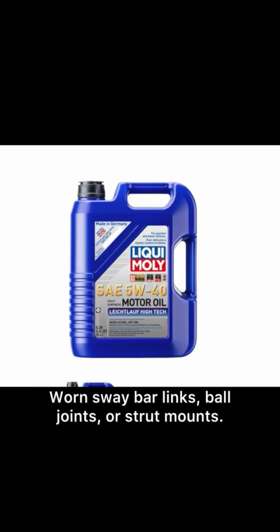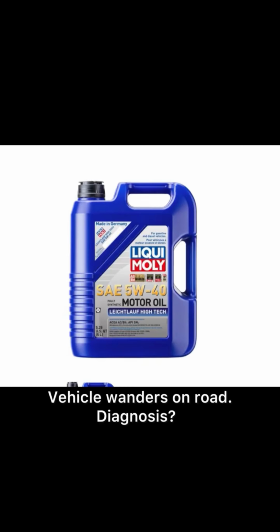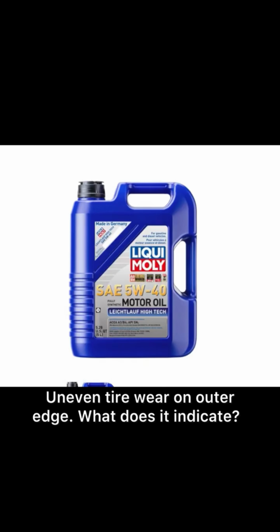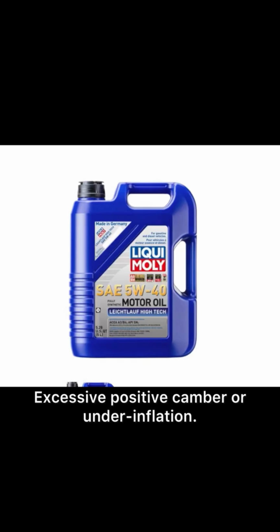Clunking noise over bumps. Likely cause: worn sway bar links, ball joints, or strut mounts. Vehicle wanders on road. Diagnosis: worn tie rod ends, loose wheel bearings, or incorrect alignment. Uneven tire wear on outer edge. What does it indicate? Excessive positive camber or underinflation.